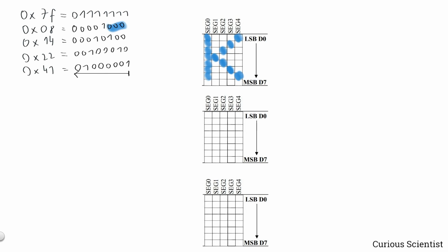And to be sure that we are doing something right, let's select 2 other characters. So let's make this capital M, and that is 0x7f, 0x02, 0x0c, 0x02, and 0x7f. You can see that along this line it's symmetrical because the letter M is symmetrical.